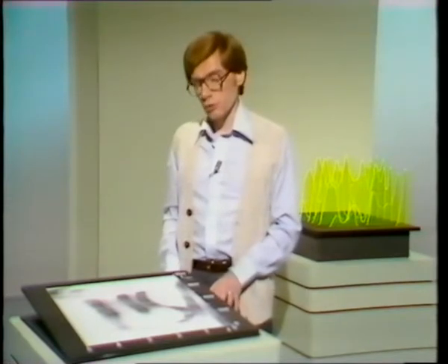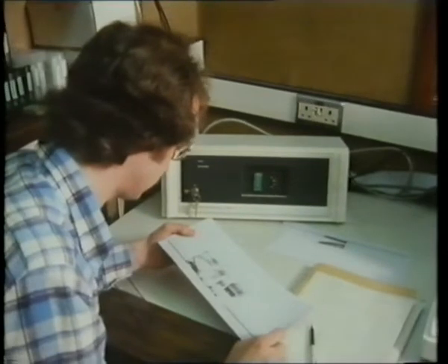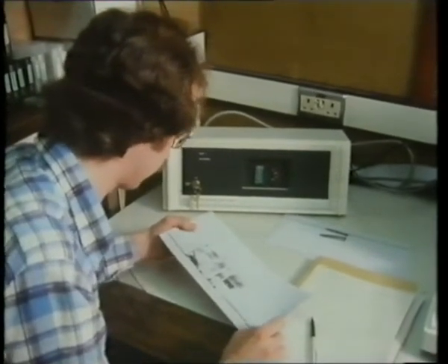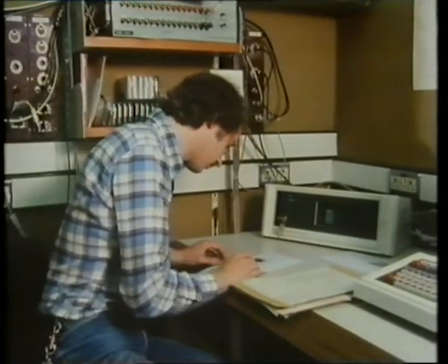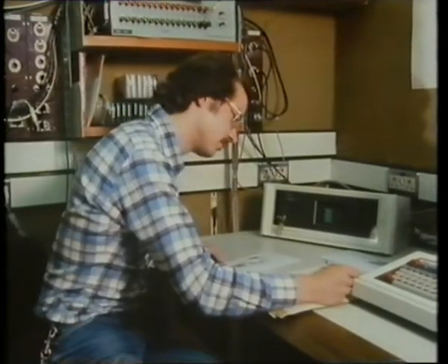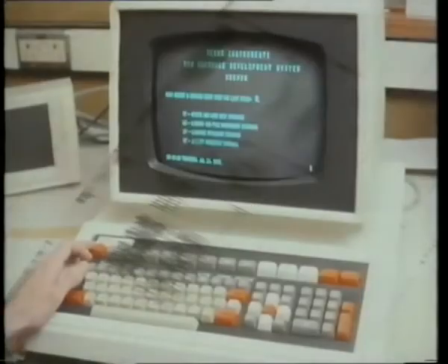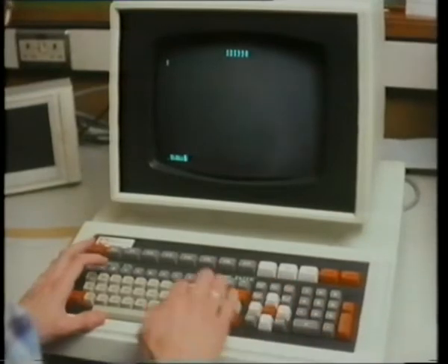But we don't work with spectrograms of this size. They're produced on a more manageable scale. This is a spectrogram of the word goldfish. And I'm going through it step by step to get a set of the filter frequencies and amplitudes as they move in time. Here I'm looking for the important changes as well. And here from the I to the sh part of fish. Now this information could be sent to the computer, which ends up controlling the synthesizer.